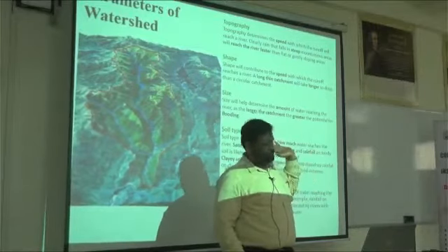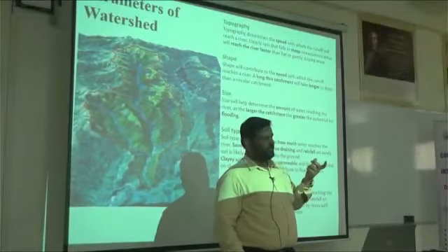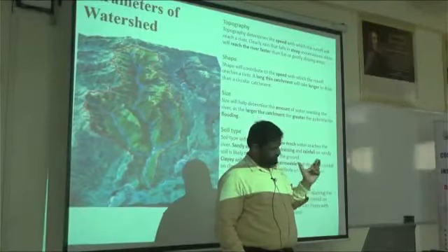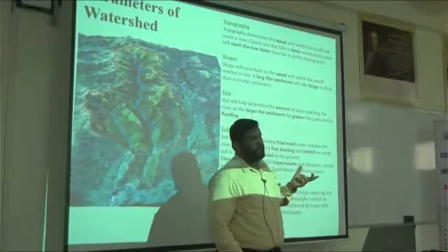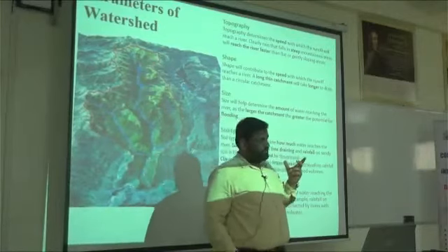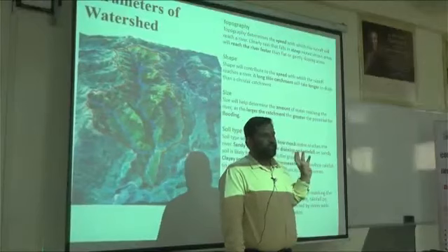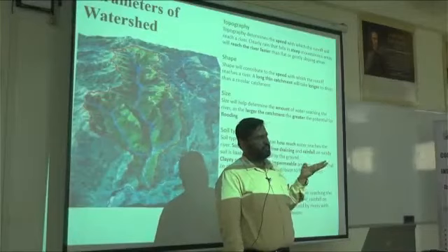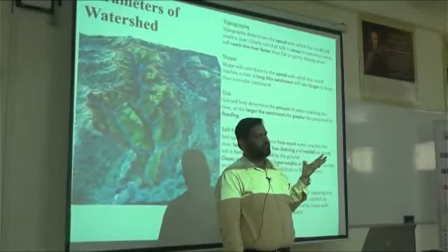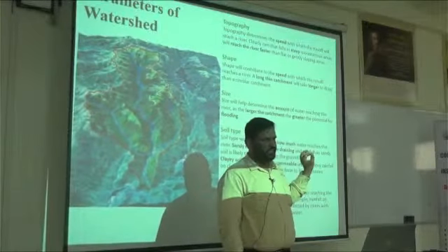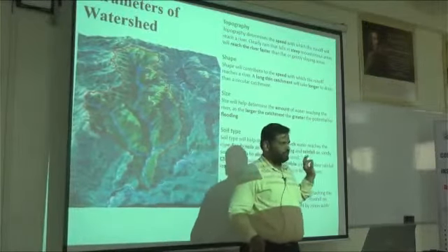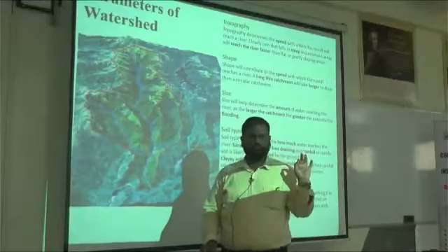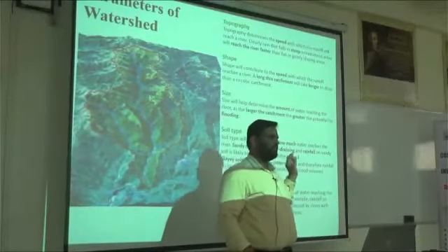Then again, shape would also be one of the major factors which contributes to runoff volume generation, the quantitative size. Similarly, then the soil types. Again, the runoff characteristics would majorly depend upon the type of soils. Like if you have gone through any engineering hydrology books or hydrology related books, they have divided hydrological soil groups into 4 types. That is A, B, C, D. So how have they classified that A, B, C, D group? Which type of soil would give you more runoff or less infiltration?